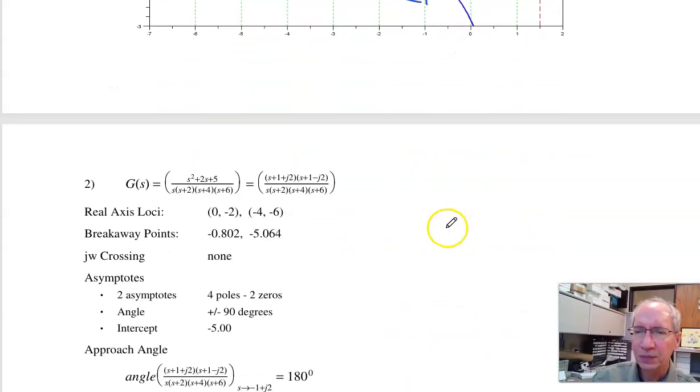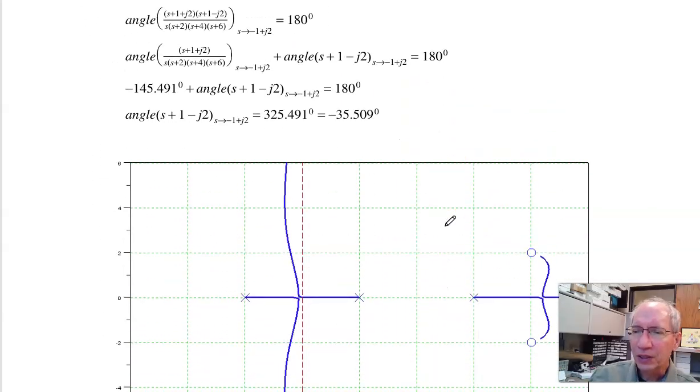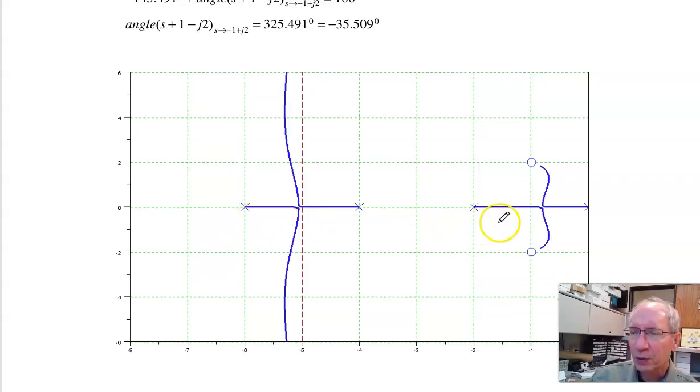That's the root locus. Complex zeros are similar. So here I've got 4 poles, 2 zeros. Real axis loci, poles come together. So there's even, odd, even, odd, even. When there's an odd number of poles and zeros to the right, I'm on the real axis loci. Breakaway point is right in the middle, pushed right by these minus charges. Poles act as minus charges, zeros plus charges. So it's the midpoint, pushed right, midpoint, pushed left.